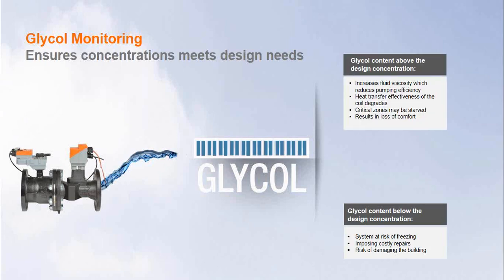Glycol concentration above the design limits has a really bad effect on the heat exchange, for one, and for two, it increases your overall pumping energy, because as you increase your glycol concentration above design, that media becomes thicker. That thicker media requires more pumping energy or more pump head to pump that around the building and increases your pressure drop. So that increases your overall pumping energy.